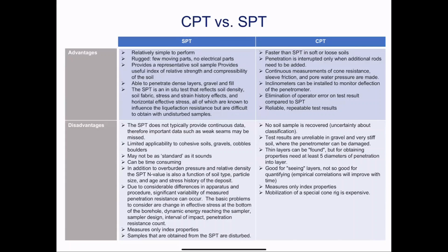Now, even though we mentioned that you can detect lenses of silt and sand, this may not be the case if this layer is too thin, because the rate of penetration might exceed the scale of the permeability for diffusion, and you might not even detect it. So that's perhaps the limitation of CPT.